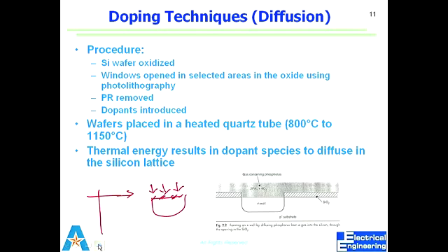So we can do many things once we start, but once we are having many of these diffusion layers, we don't have too much thermal room to play with. Or what we can do is calculate that diffusion, and we would know, okay, if I do another 1000-degree process for 10 minutes, this is going to diffuse in this way. So I can start with a certain number of dopant. After those 3-4 steps, I would end up with what exactly I wanted there. Does that make sense?